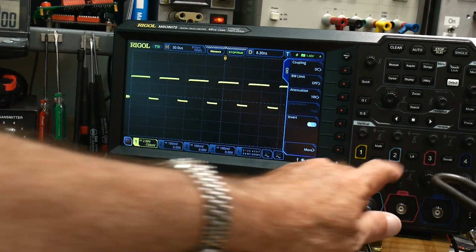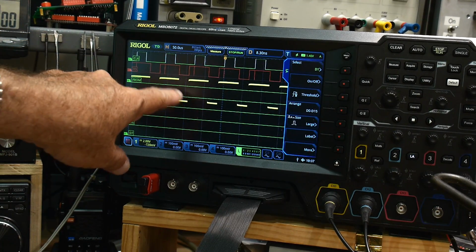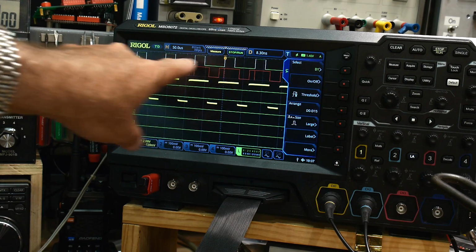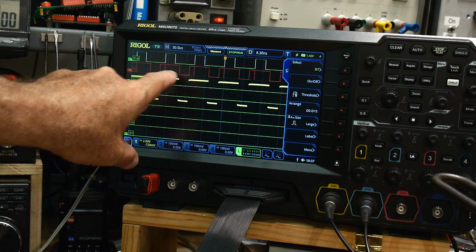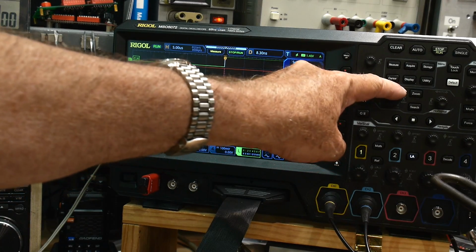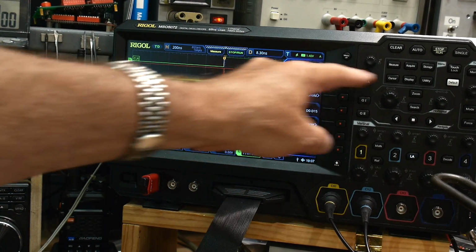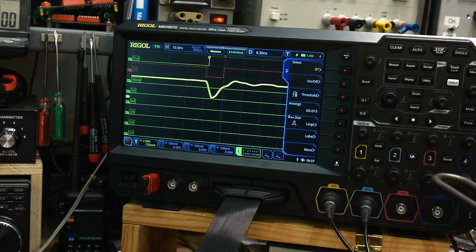So let's go back up to this, and let me turn on the logic analyzer. You can see this was our original analog signal, but here's our digital signal. You can notice something funny on that red trace there. It has a glitch in it, right? If I zoom in a little bit farther, you see this glitch. If I zoom way in on it, and even further, you can see that the analog signal glitched there.